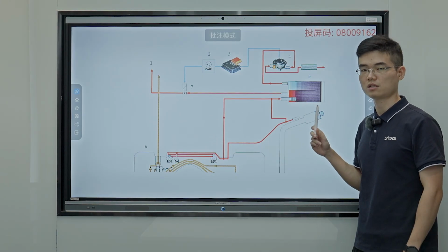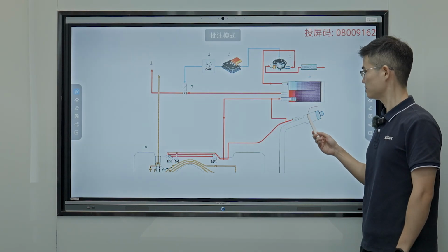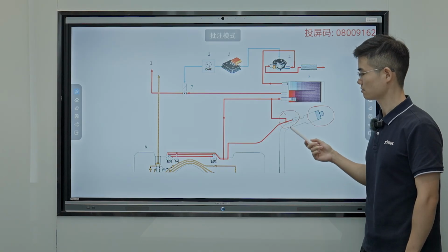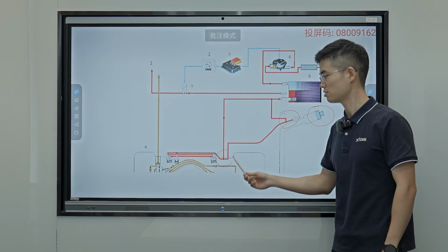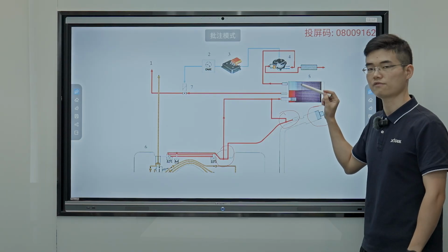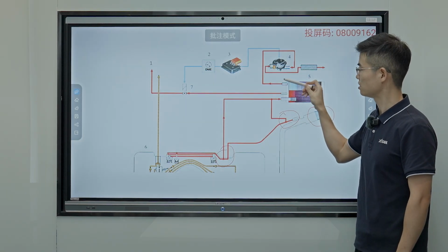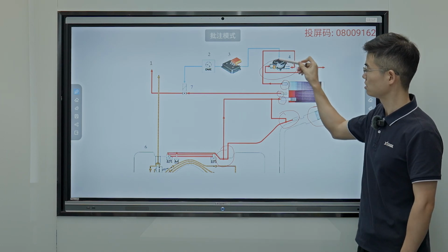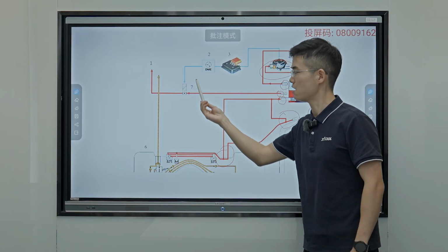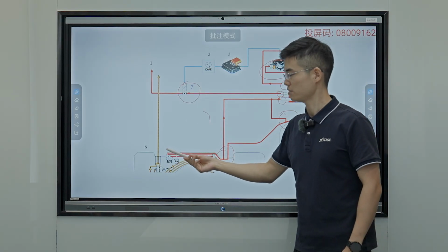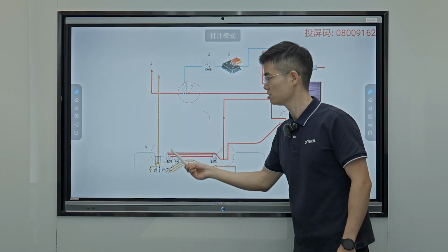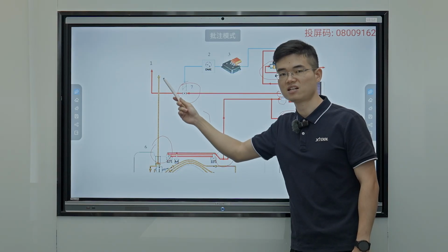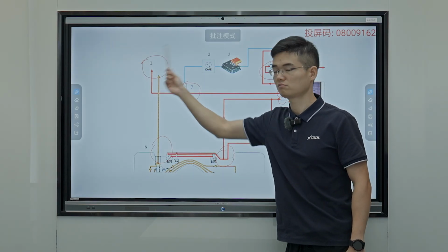The first is the fuel tank filler cap, then the vapor pipe joints, the tank joints, and the joints of the activated carbon filter, the NVLD pump, the fuel tank vent valve, the fuel tank pump joint, and the last one is the motor intake manifold joint.